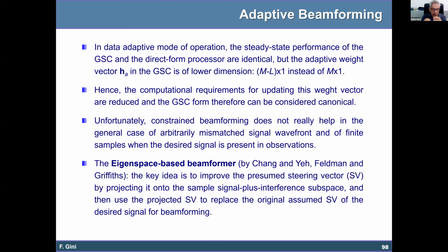basically you have two channels. In one channel, you measure the power coming. Basically, in the side lobe canceller, you have a small omnidirectional antenna with a small gain. And the purpose of this antenna is to understand if a signal is coming from the main lobe or from a side lobe.